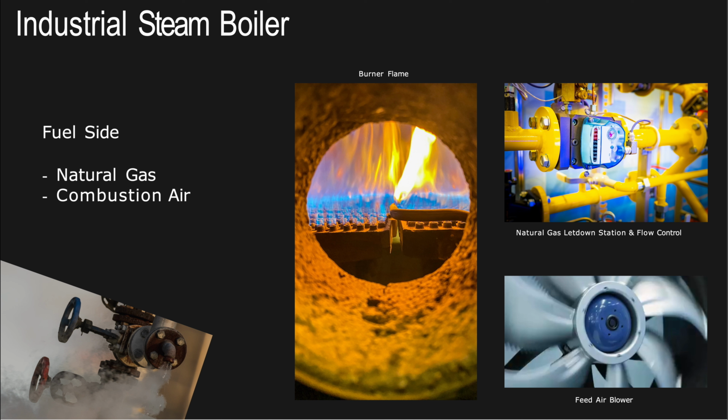If you ever get the chance to be by any sort of steam boiler, there are glass spots where you can actually look at the burner from inside, and that's how operators would know if the burner is on, because if it's not, that's going to be a big trouble. If you have gas and there's no ignition, that's going to be a problem because that's an explosive enclosure.